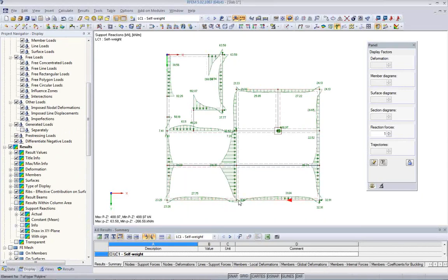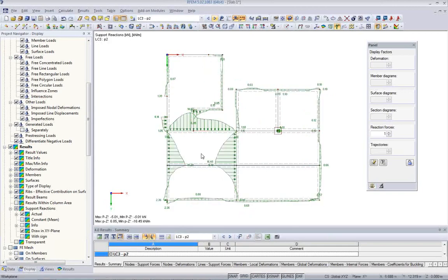So I can kind of swap them over, and then I see the support reactions here in a much better view. Often engineers do not work with the real lines of the support forces because when there is a masonry wall, the force transfer is not one-to-one from the support of the slab down to the next maybe wall below.